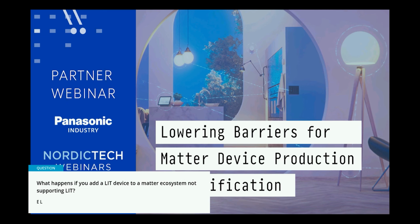What happens if you add a LIT device to a Matter ecosystem not supporting LIT? It's just going to work as SIT with the biggest interval allowed for SIT, so 15 seconds. As I presented in the demo, an ICD LIT always starts as SIT and waits in that state for registering the first ICD client. If the ecosystem does not support LIT, it will simply not register as a client, so the device will keep working as SIT.